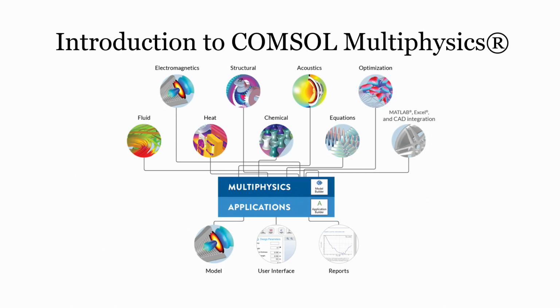When you talk about COMSOL Multiphysics, we will be discussing the details in one of the classes about how to use this software, but for you to understand what the applications are and where you can use this particular software: the first one is in fluid dynamics. You can use it to understand a microfluidic system and the fluid flowing through a particular channel. You can use it in electromagnetics. You can use it in heat. If you take an example of a heater, you can easily understand.